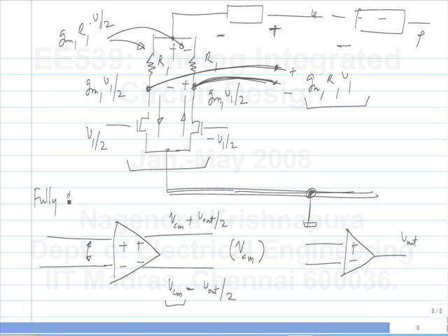By the end of the course, hopefully you will have learned how to make these things. Now with this, you can have op-amp circuits in which all signals are fully differential. This is the way circuits are normally done on an IC today. You don't use a single-ended circuit unless there is a particular need. Sometimes you have to drive a single-ended output, like a speaker. Then you don't necessarily make it fully differential. But inside the op-amp for signal processing, it is best if you make it fully differential.